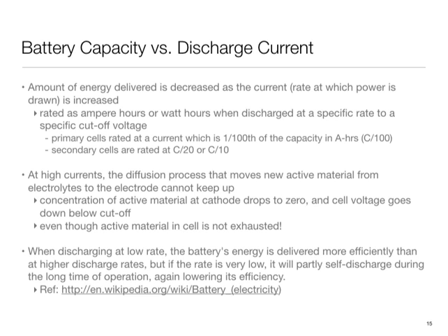And that also explains the relaxation process. Now I stop doing it, and that electrolyte inside the battery evens out, and it builds up again near the terminal. So the queue near the terminal again replenishes, and now I can again draw material from it. So that's the under-the-hood physical process that explains both these things. So at high currents, the diffusion process cannot keep up.